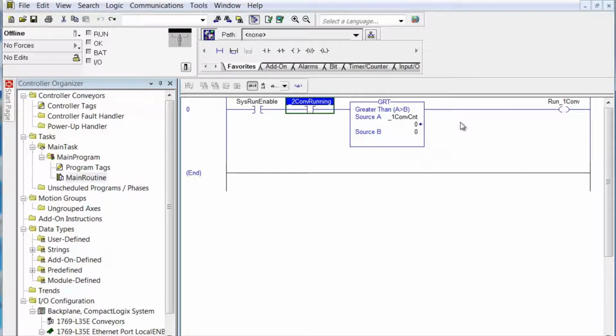One of the nice things about RSLogix 5000, it is actually easier to maintain consistency than it was in RS500. In RS500, you basically, every time you created something, you were doing it from scratch, where you will see later on in this lab that it's real easy to reuse things even with the same tag name, because of the isolation between one program tag database and another.